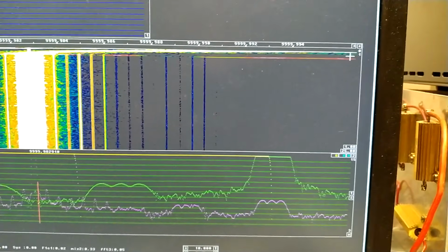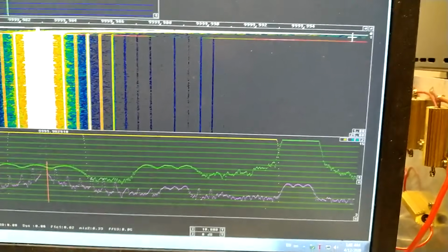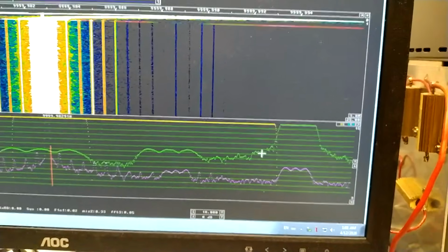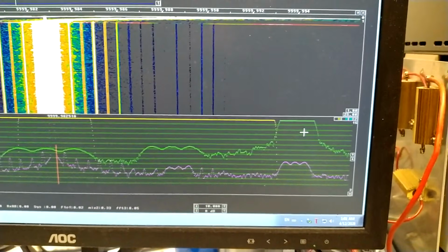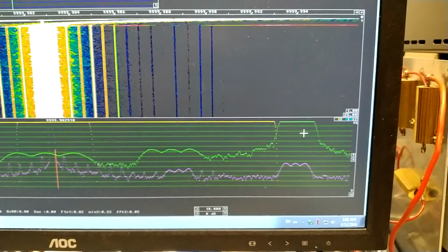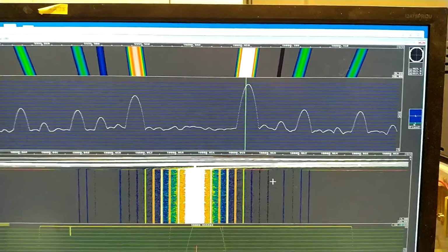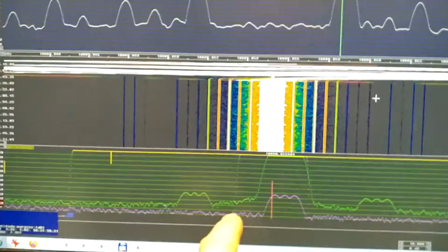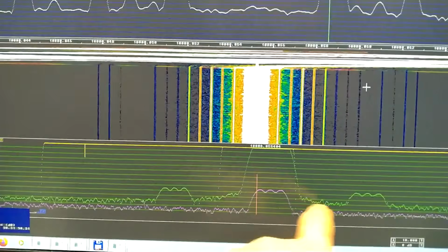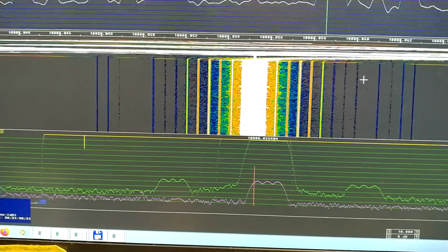You can see the noise up here and also here. I will shift the frequency to the other side of the frequency scale in the baseband. The frequency has drifted by about 70 Hz now, and the phase noise of channel 1 is unaffected. It is still as strong as before.